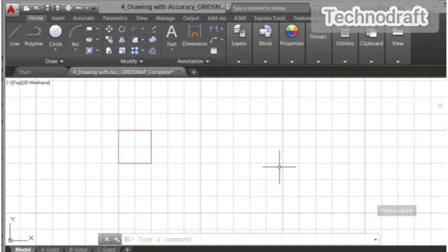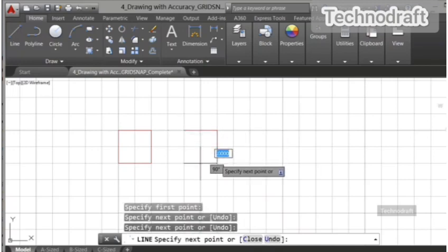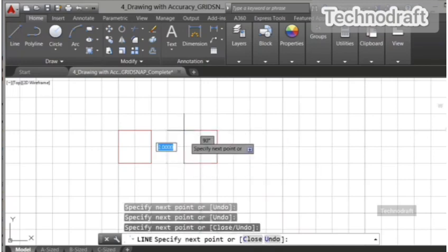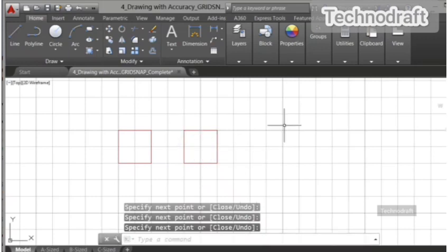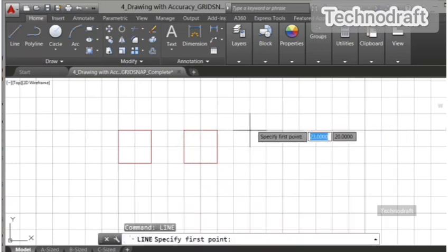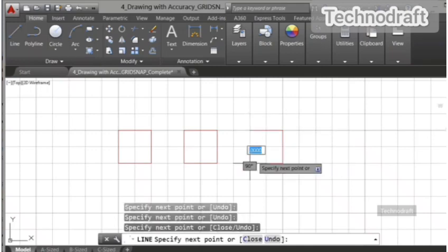Okay, then now you can see that it stands out nicely on the white background. It's amazing what you can do with slight changes of colors in AutoCAD. And then what we will do now is draw some more squares. So I will go back to the line command and draw another square like this, and I can start creating an organizational flowchart like this.